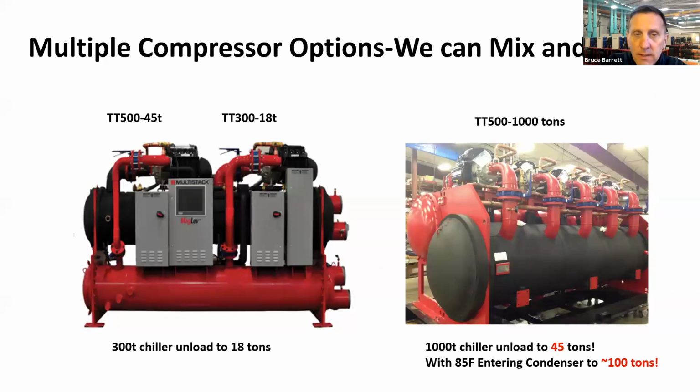Typical turn down is 40–50% of your design flow. But one of the control benefits that we have is also rate of change. We have a 40% rate of change per minute that our compressors can adjust to. So if something shuts down the system really quickly, we can catch up with our compressors.